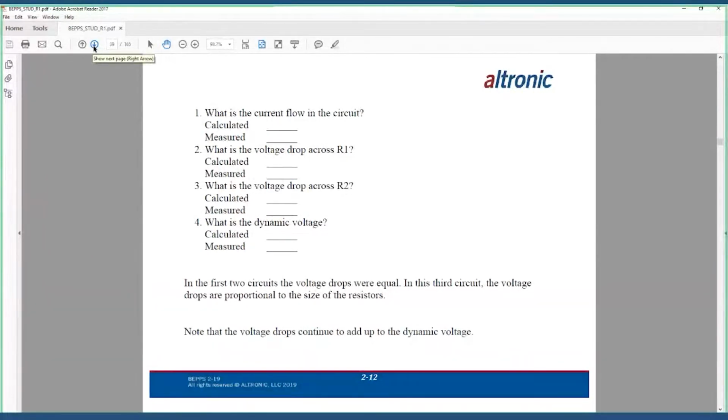This is where I really need a volunteer to chime in here, but I can do this: 9 divided by 11,000 ohms. There's not much amp draw here. 0.00081, and we'll just round it off and say 81. That's close enough.